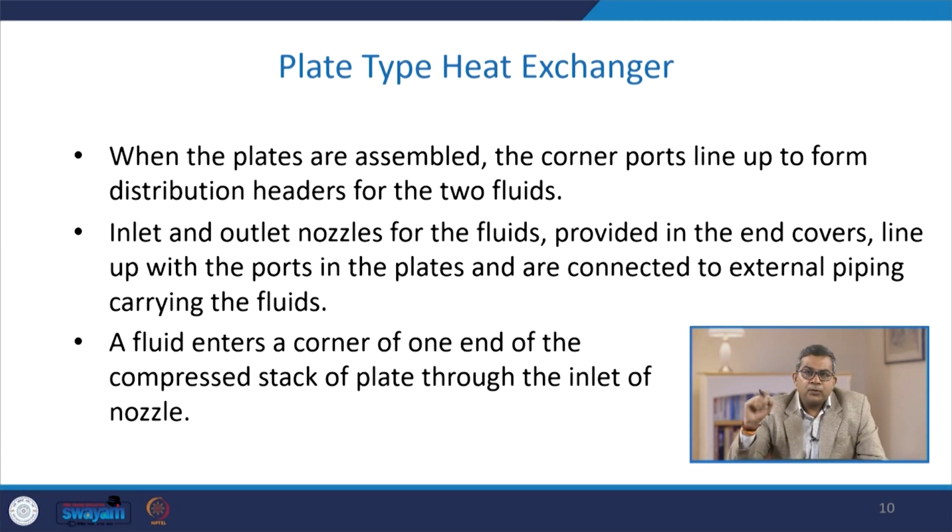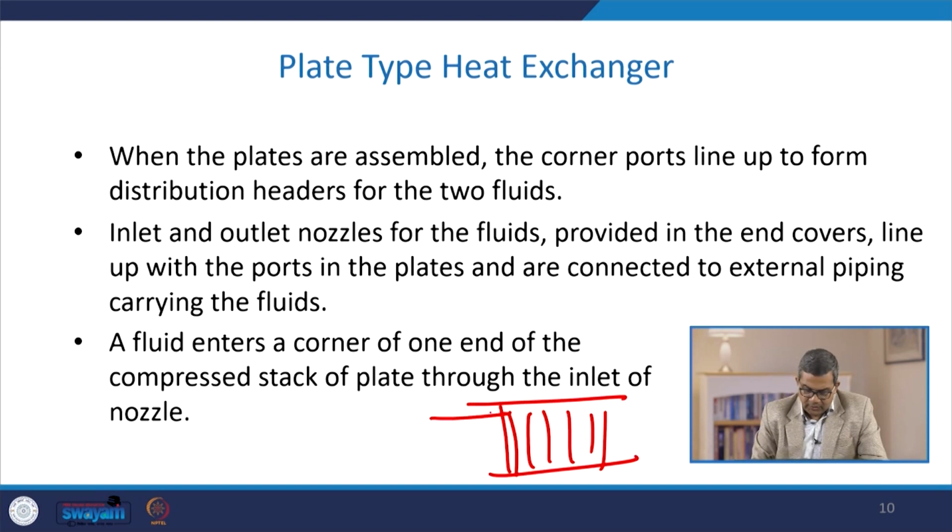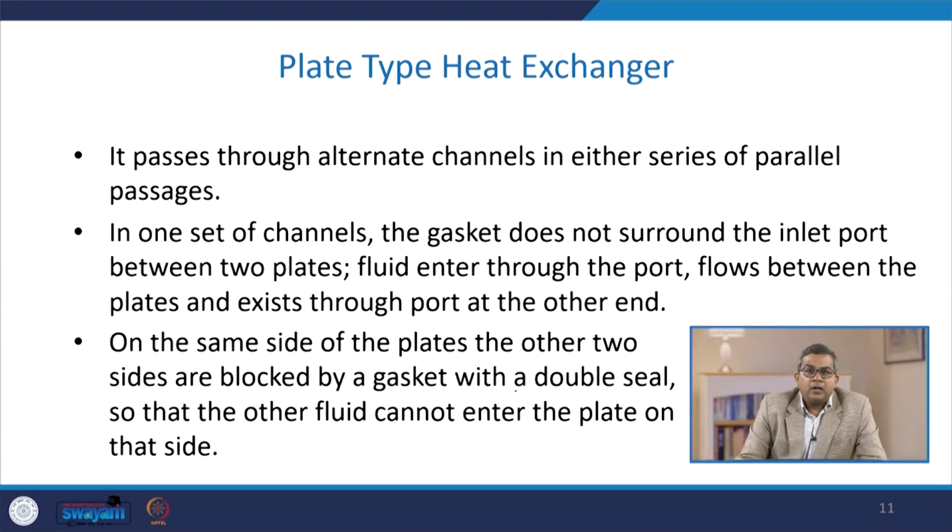Now, a fluid enters a corner of one end of the compressed stack of plates. So, these are the compressed stack plates. The fluid enters from a corner of one end of the compressed stack through the inlet nozzle. Now, it passes through alternate channels, maybe in a series of parallel passages.